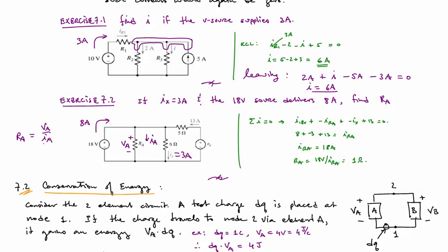It just so happens that that resistor is in parallel with an 18-volt source. Because they're in parallel, by KVL, which we haven't looked at yet, the voltage V_A is just 18 volts. So what I really need to find is just I_A. How can I find I_A? We can write a KCL equation for this node up here. I think we have all the other currents identified.